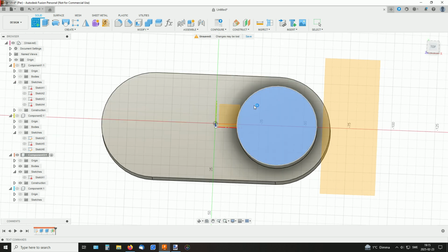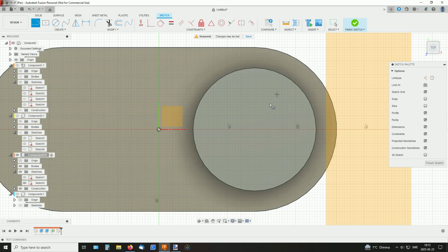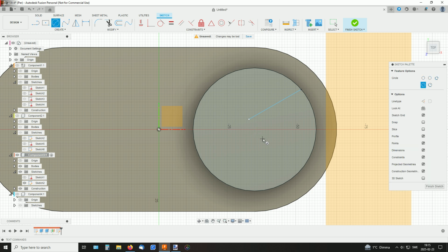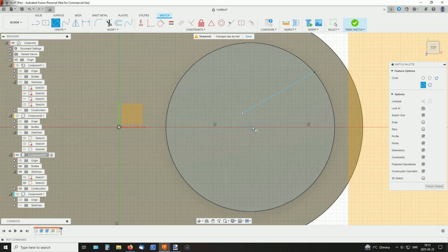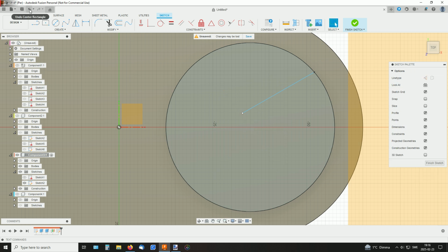If I make a sketch over here at this face, now I can grab onto the edges here directly. The edge is auto-projected. And if I wanted to create a circle, I also get this center point, or anything really. I have this center point auto-projected as this is a circle. So I can make sure what I create is constrained to the center of that circle. Let's undo those.